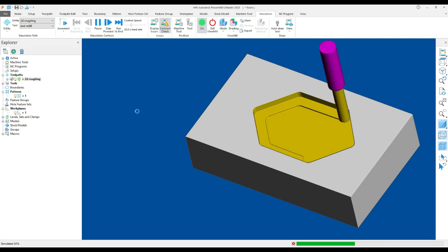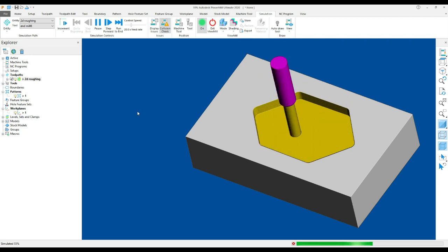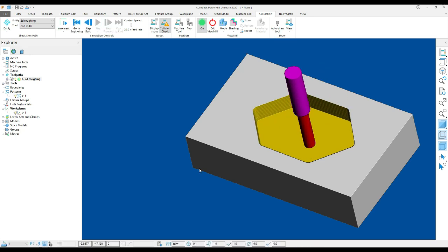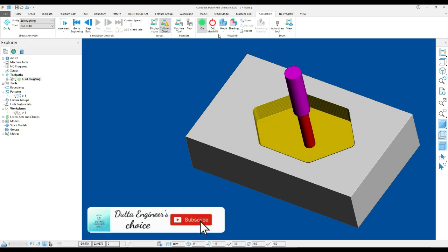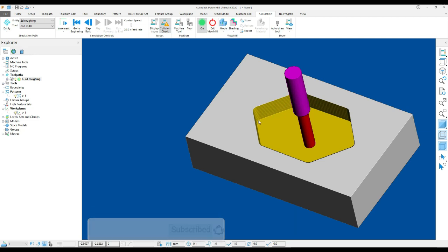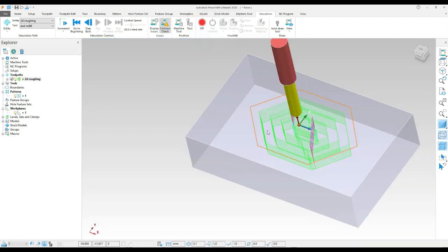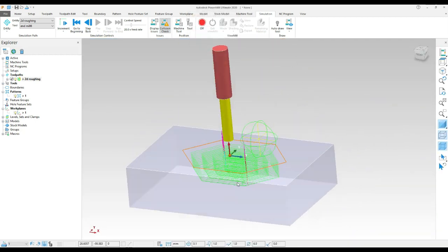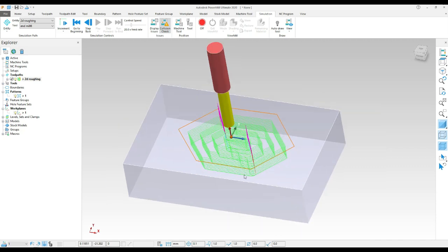And I mentioned before that there is a draft angle, so here you can see our toolpath has the 2-degree draft angle and the 1 mm curve thickness on this wall. It is clearly visible, friends. This 1 mm in these steps we remove in our finishing toolpath. So I just exit it, and this one is our 2D curve profile toolpath, friends.